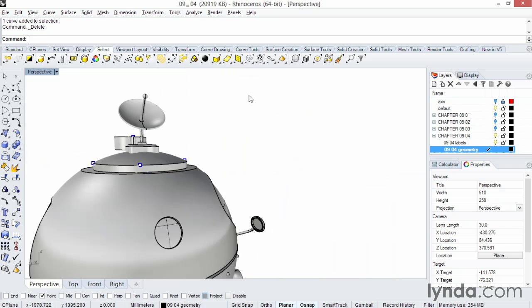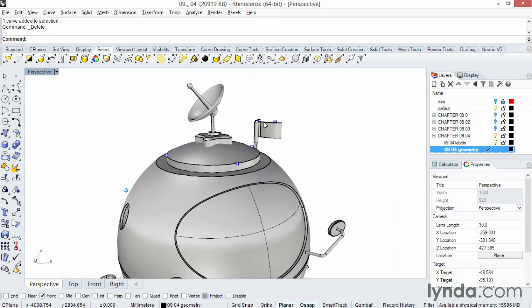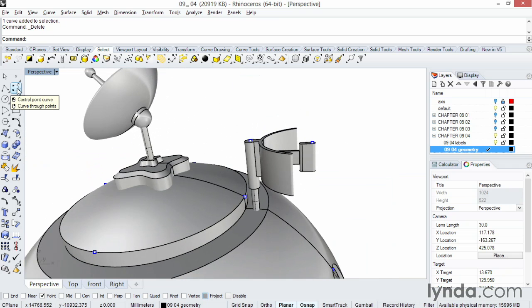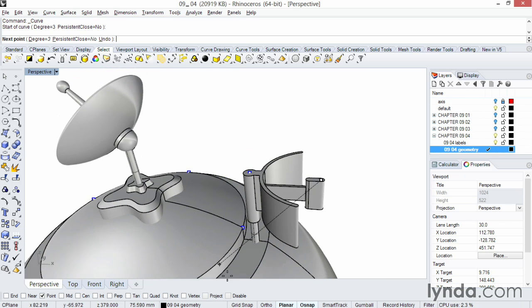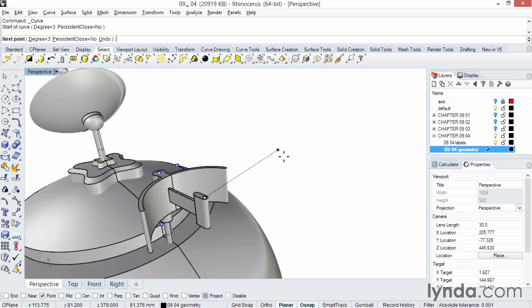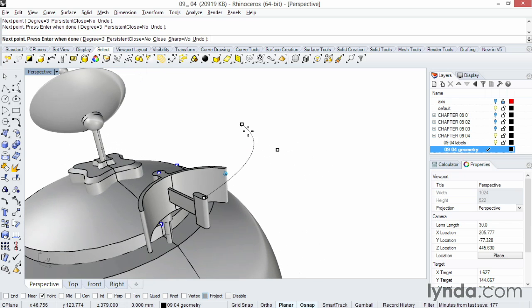Double-click the perspective viewport to maximize. Do that same curve again. So I've got the point snap on. Let's actually be careful. You don't want to turn this on before the first point because it'll start projecting to the construction plane by default. So let's keep that off. Start the curve. Now turn project on. And so it'll be maintained with the planar O-snap. It'll maintain the same level.